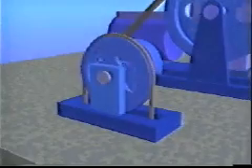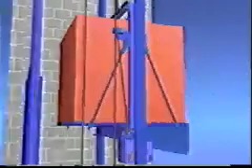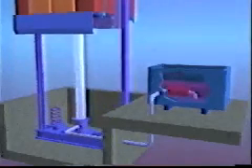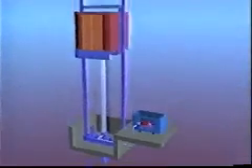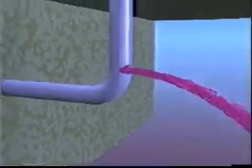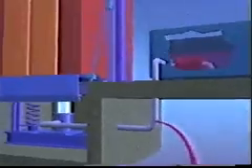If the car speed continues to increase in the down direction, the governor then sets the safety. Remember, safeties of this type are found only on traction elevators. Car safeties and governors are not required for hydraulic elevators because they can descend no faster than oil can escape from the system.